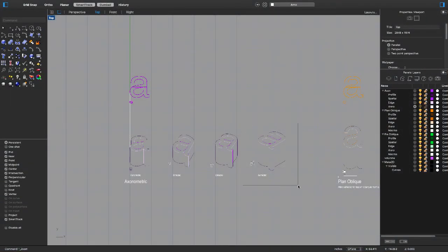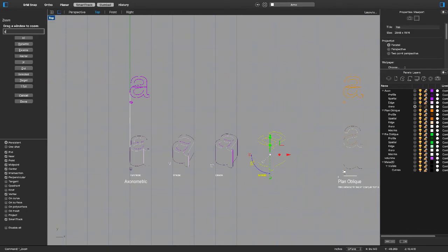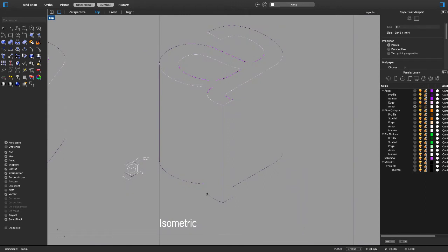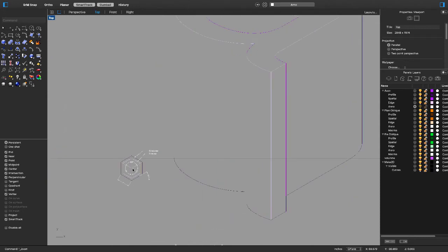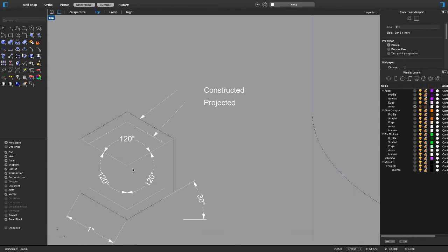First, we have the isometrics. All 3 principal faces are equally inclined to the picture plane and are foreshortened equally. Note that a projection foreshortens the drawing, noted by the outline here. In order for the drawing to become measurable, we must scale up the drawing slightly. In an isometric drawing, all 3 principal axes are 120 degrees apart on the picture plane.